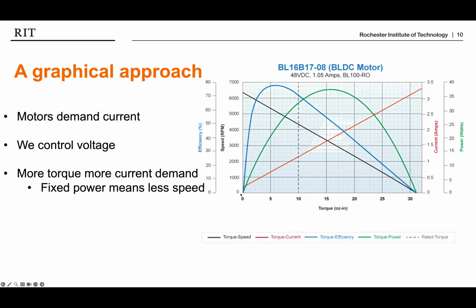I bet there's some calculus involved here, folks. This line with a constant slope is going to generate a parabola. And that is true. This whole parabola comes out of the fact that there is this kind of coefficient that connects torque and speed. And sure enough, there's a point up here where my power should be, give or take a little bit of efficiency, right about the midpoint of the speed and torque curve. And yes, indeed, right about there, I would say, is indeed my peak power.